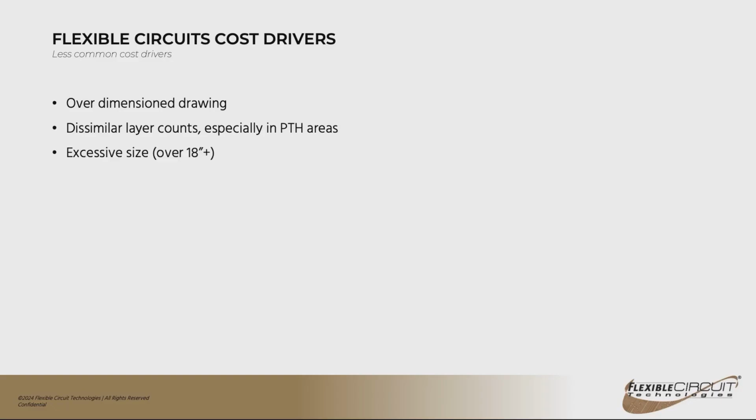If you have a large circuit, it's going to have an impact on the cost up and beyond just the size of the footprint that it's taking up on the processing panel. As I mentioned earlier, manufacturers have standard panel sizes, and if your part does not fit on that standard panel size, it's going to require some significant changes in their processing in order to build the part, and that's going to definitely increase the cost of the circuit.